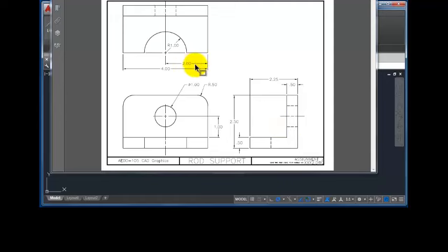If I take a look at this area here, I've got to decide, is this inches or millimeters? If this were millimeters, this object would be very small, so inches makes more sense. I could also take a look at the position of the zeros in these dimensions. If there were zeros at the front, they're called leading zeros, this would likely be a metric drawing, but where they are trailing zeros, zeros at the end, this is most likely an imperial drawing.